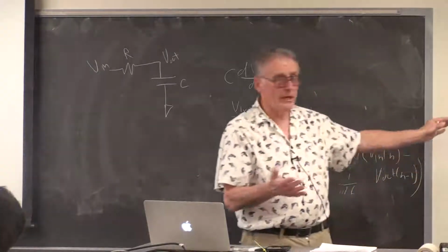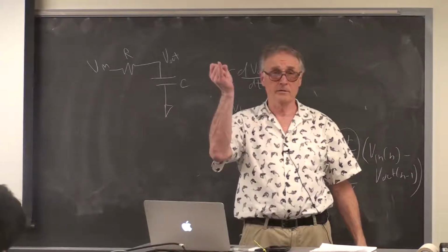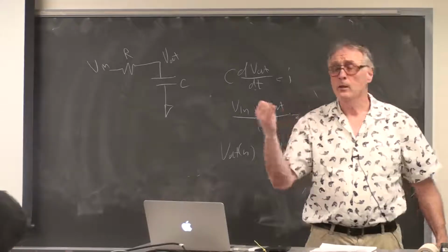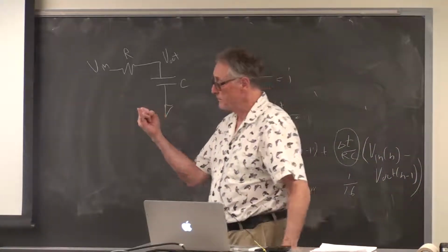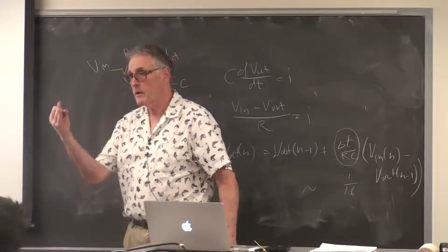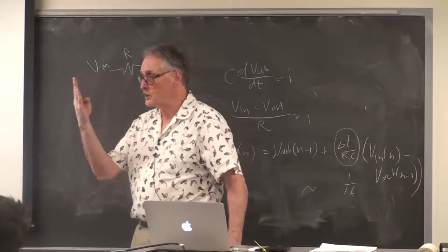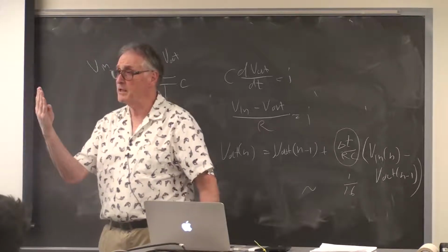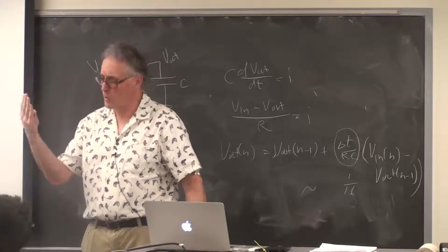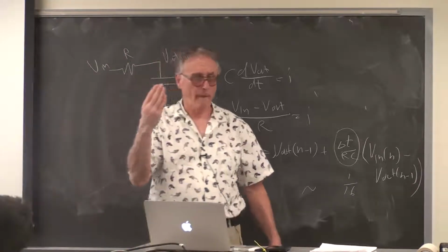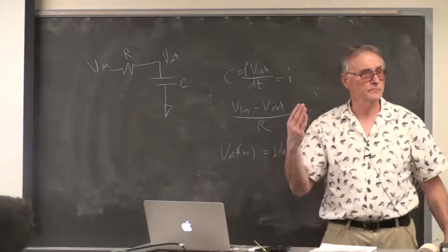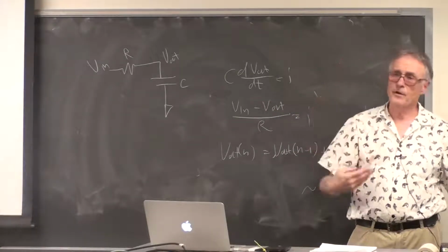So you're going to calculate a PID function in the interrupt service routine. You're going to read the ADC. You're going to calculate a PID function. You're going to update the PWM. Then you're going to update 2 DAC channels, one for angle, and one for motor speed control voltage. And then bail out. So it's going to be a very fixed routine.